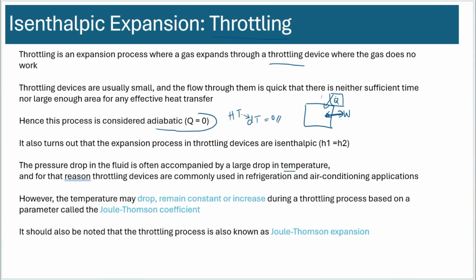Okay, so first of all, isenthalpic means H1 is H2, and we'll get to that equation really quick. In most textbooks, they will just define Q equals 0 and isenthalpic, but we should derive that from the first law of open systems.